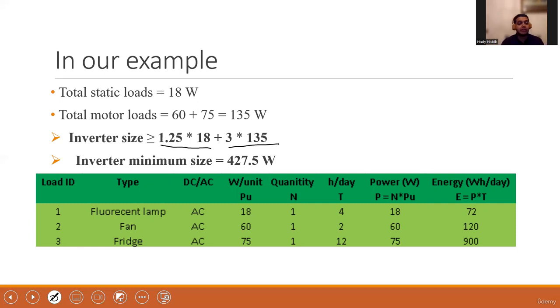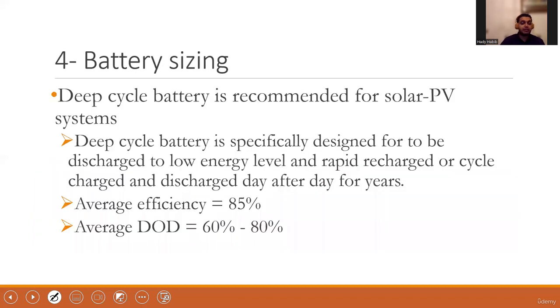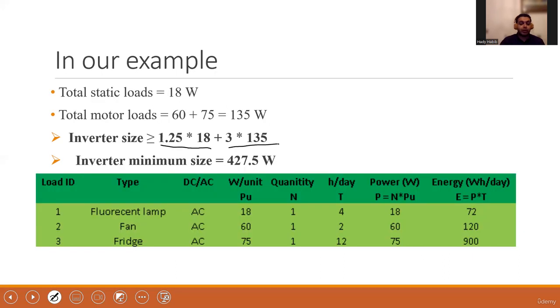So we are going to have at least 427.5 watt as the minimum size of the inverter. So our inverter should be greater than this number.